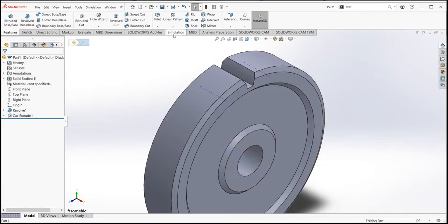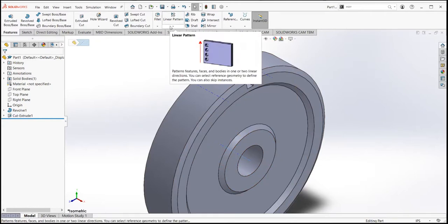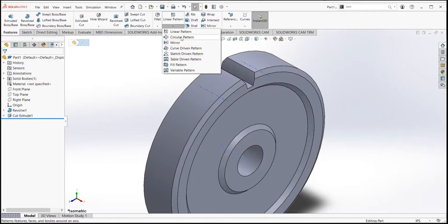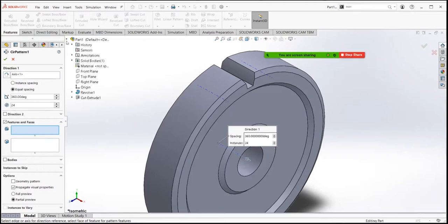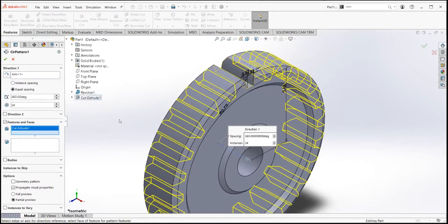Now we can go to circular pattern, select this entity, go to select circular line. It's already selected as the axis and we want it to be equal spaces. So the number of teeth is 24. The feature will be the extruded face. We just did it. So go to extrude one and select it. It will highlight that it performed it. Click on yes.